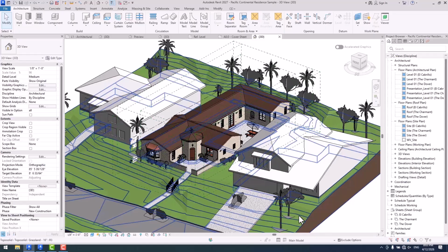Like, for example, in some projects, when dealing with single family houses, they might prepare tens of different alternatives or design options within a single file. Now, they have to do this due to some small yet required changes. Like, for example, within one type, a wall might be removed, or in another, a window might be relocated. Now, in such cases, instead of creating a completely new file, they would keep the main structure. I'm talking about, for example, the site, the main structure, the fixed surrounding areas, and then the changes would be presented as design options.